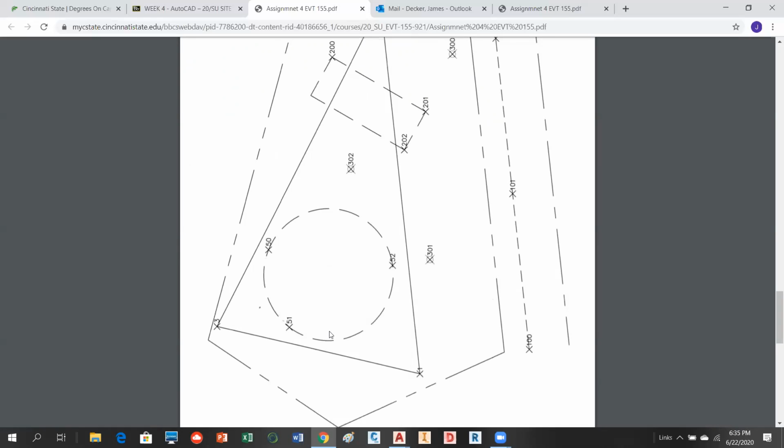So does anybody know how I'm going to draw this tank based on those 3 points? Nobody has a clue? Say that again. Would you use the, not the tangent? It's one of the O snaps, right? Well, you're going to use an O snap. That's important, okay? And I didn't talk about that. But what command would you use to actually draw that circle? A 3-point circle. Absolutely, a 3-point circle, okay?